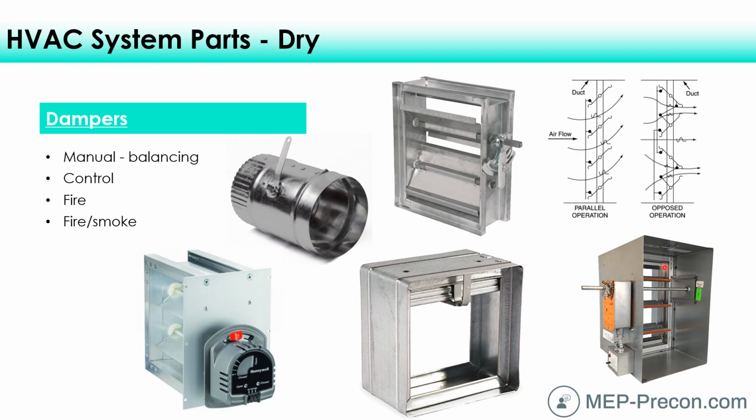These are pretty expensive, not only because of the way that they're built, but also because they'll take an electrical connection from the electrician, not just the controls contractor with low voltage wire in this situation, but there's some interface with the fire alarm system and with electrical, and so the whole total installed cost for this fire smoke damper is usually pretty expensive.